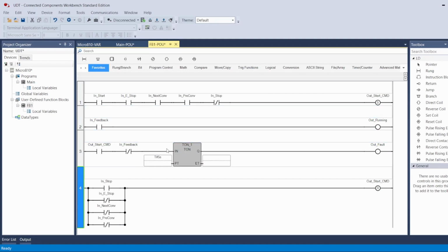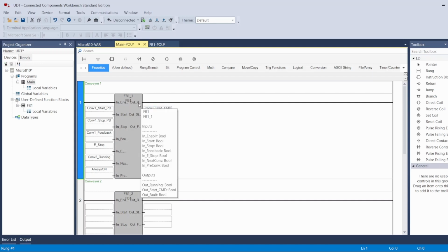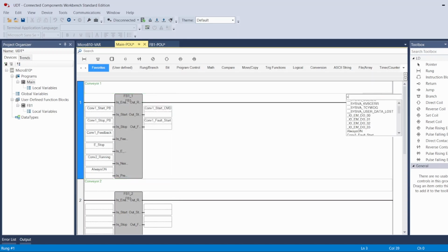And when this starts, I should be receiving this signal, conveyor 1 start command. It should turn on, and this should go to the physical output that turns on a drive or motor. And the faults, if I have any fault, yep, it gives me false start. Running now, which is the first signal here, when this turns on, I want it to give me conveyor 1 is running.